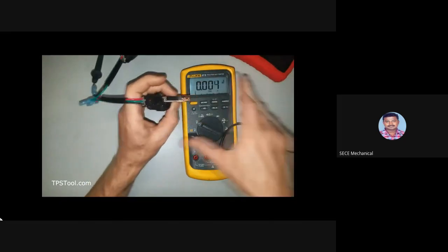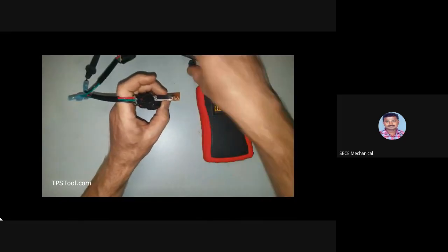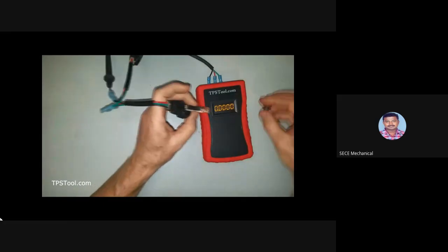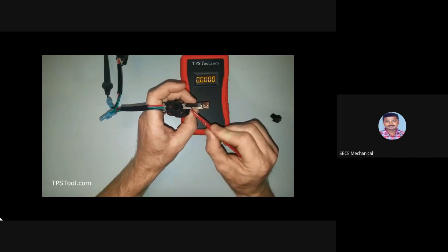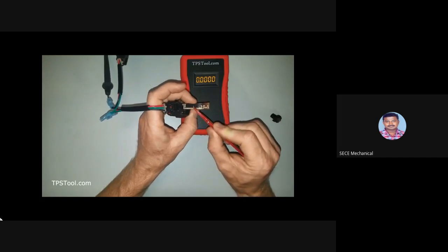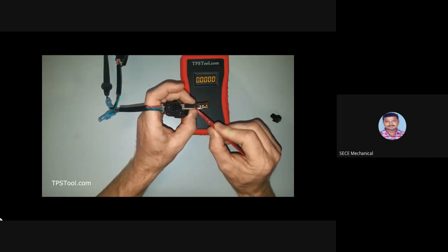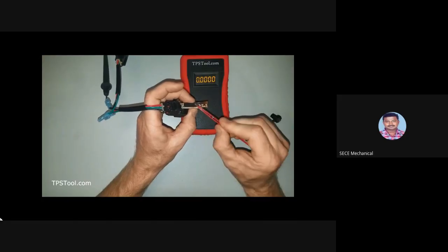So let's see if we can do it now. Come back here since it's all connected and use our wiper. Maybe I can do the wiper. So what this actually does is connects the part of this conductor that we're interested in reading with the second conductor. And the second conductor is just for reading. Practically no current flows through the second one at all. It's all just for voltage. So this is the one that current flows through.